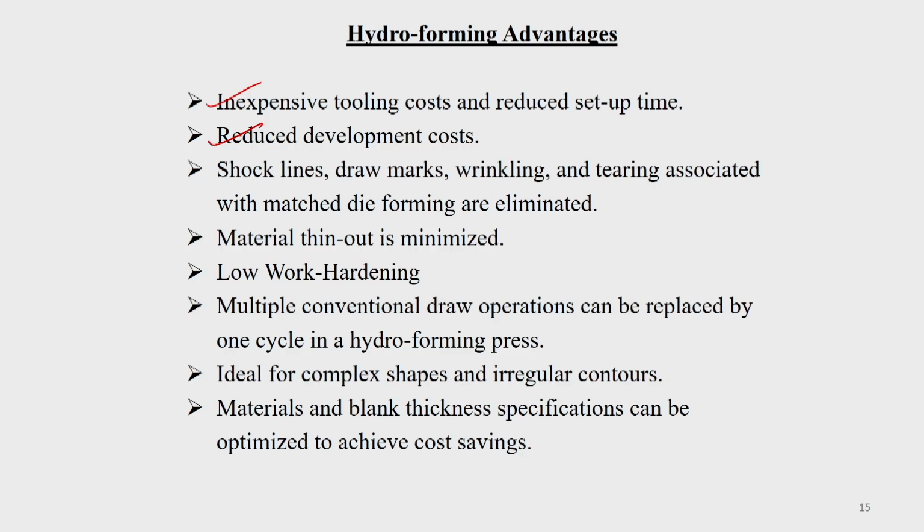Then the shock lines, draw marks, wrinkling and tearing associated with matched die forming are all eliminated. These are not going to happen because of the hydrostatic stress. Wrinkling will not be there, draw marks will not be there, shock lines will not be there, and maybe some tearing also, because of the hydrostatic pressure. So, the tearing also may be eliminated.